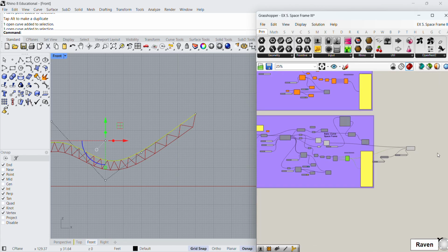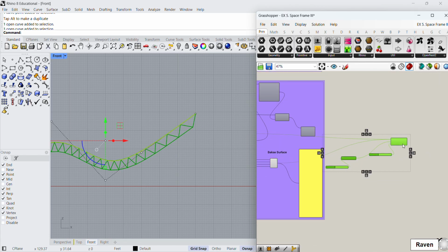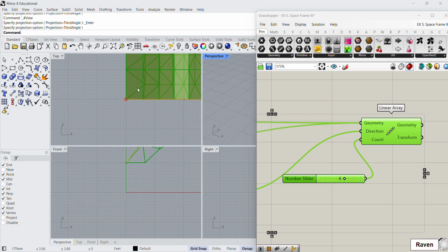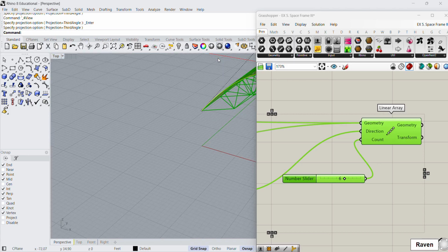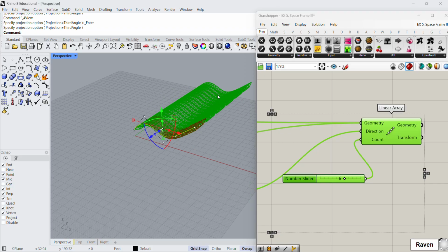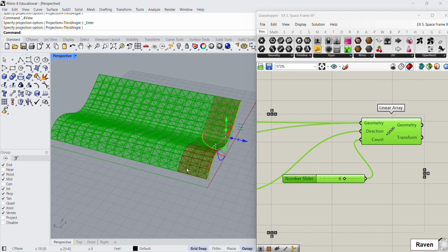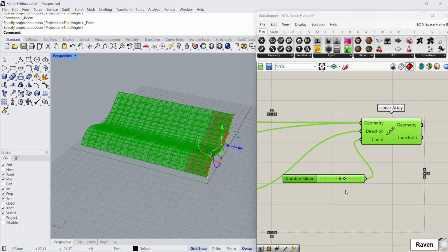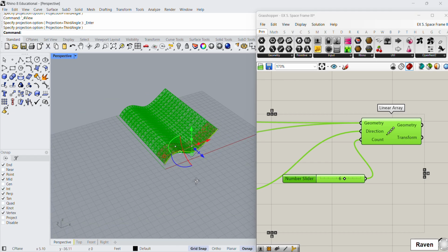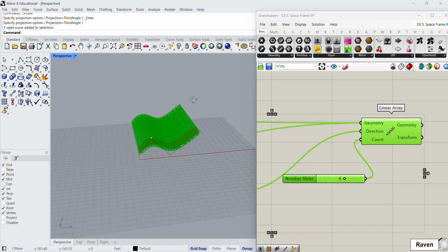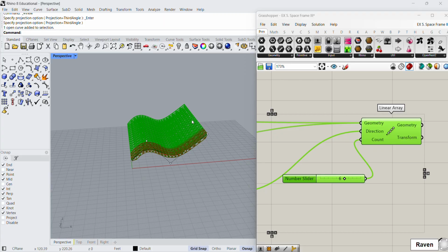After that, I add one more step. Whatever truss I built, I copy over 6 times in the Y direction. So instead of just practicing with the one loop structure 30 feet wide, I'm gonna copy it over 6 times. So this is the entire truss system. I'm gonna export and import into SAP.